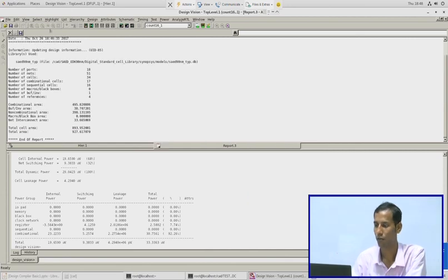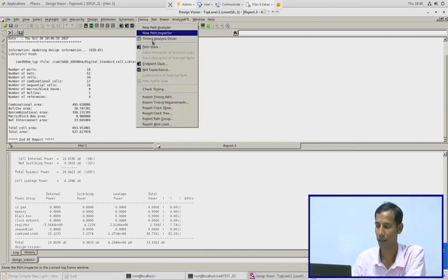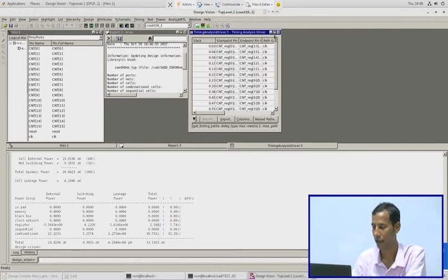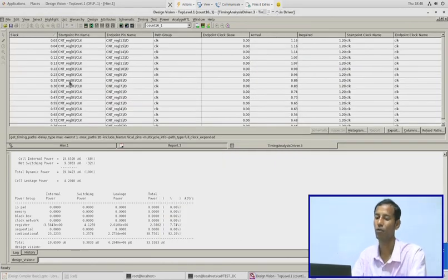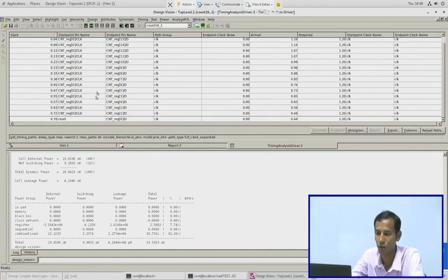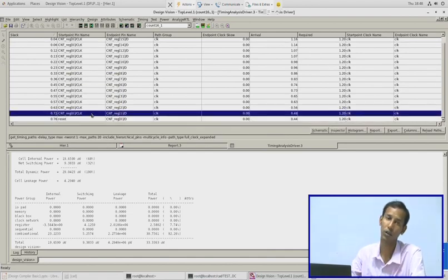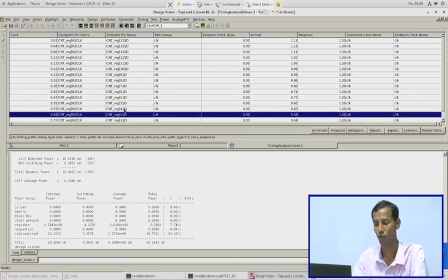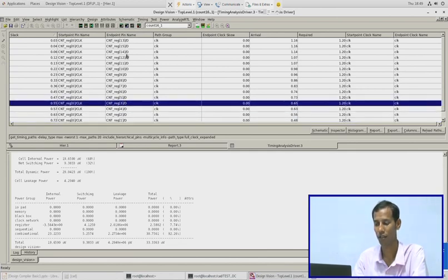After that, what I left is the timing information. If you click on the timing analysis driver, here you will get that there are several paths from inputs to the outputs, right. There is a path from clock to Q, that means 16 outputs are there. So 16 from clock, that's range 1, then range 2, then range 4, 3, 5, 6, 7, 8, 9.